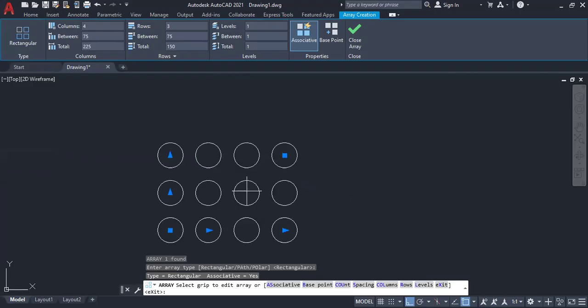Wherever uniform distribution is required, not only for lights, you can say sprinklers for firefighting systems. You will have hydraulic water firefighting systems. There you will have end sprinklers. In one floor, you will get 100, 200, 300 sprinklers also, because every 12 to 14 feet distance you will get one sprinkler. If your building is 100 by 100, definitely minimum one floor you will have 40 to 50 sprinklers.